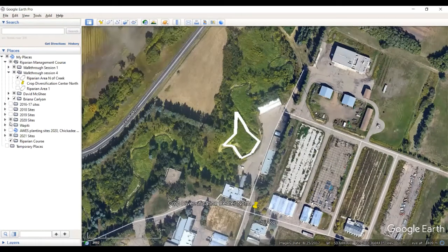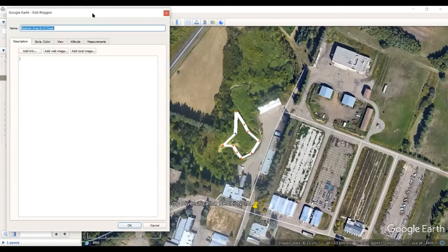But if you already happen to have your polygon drawn out, like I do here from session 1, instead of having to go through and measure everything with this particular tool, you can actually use the drawing that you've created already and get the area or get measurements from that as well. So you just find the name in your relevant project file. You'll go to the named feature that you've drawn out. It could be one of many features that you potentially have drawn out in section 1. So you're going to right click on that and go down to properties.